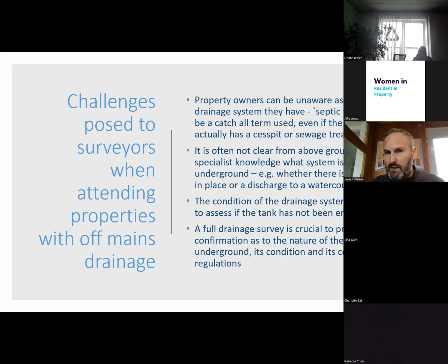It's absolutely imperative. This isn't a sales pitch for me. For any company doing these inspections, it's imperative that the system is completely emptied so that a survey can be done inside the asset itself, and then a conventional CCTV camera survey can be carried out leading away from the asset to see where it goes and to make sure it's performing, and also back to the property to make sure there's no issues with the pipework and to check for cross connections. Because as I said, there shouldn't be any rainwater or surface water coming into these systems.